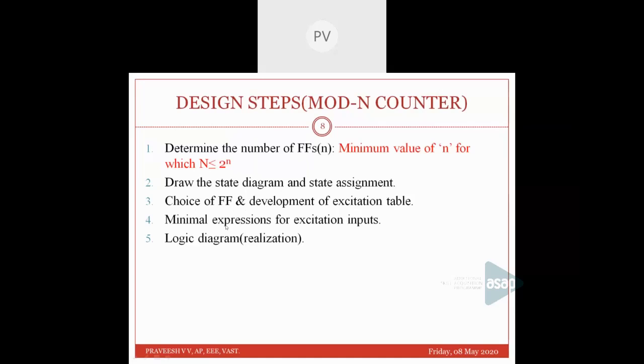Then develop the excitation table based on that flip flop. Then obtain the minimal expression using the K-map reduction techniques. Then finally you have to implement or realize using the logic diagram. So I will explain each step in detail, then we'll go to the example.